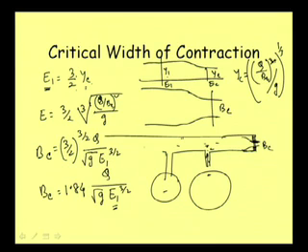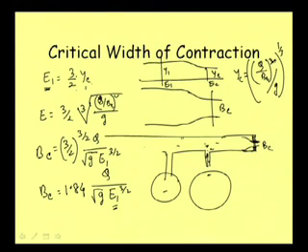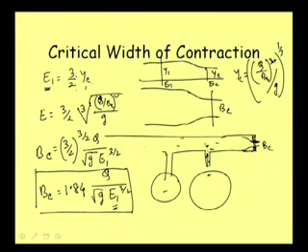Now, at upstream if we measure the Y1 we can always get this value, and of course, in some cases by neglecting the approach velocity we can simplify this expression further. That means, if we neglect the approach velocity, V square by twice g will become 0, and then we can take this as Y1. So, that sort of simplification is also done, but basically this is the expression for calculating BC.